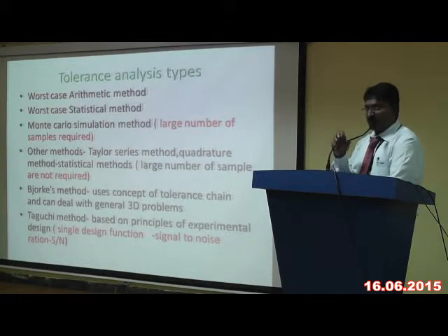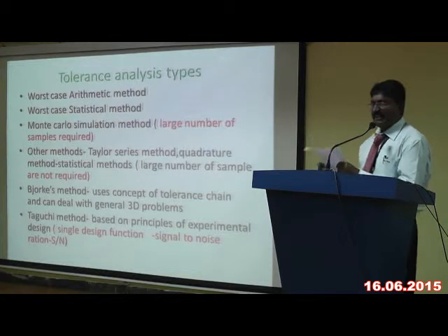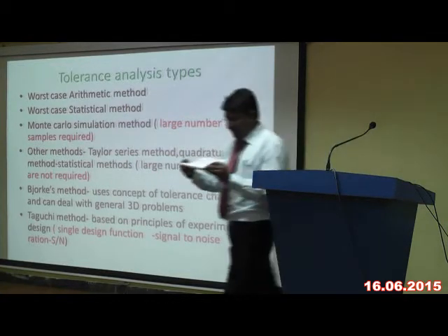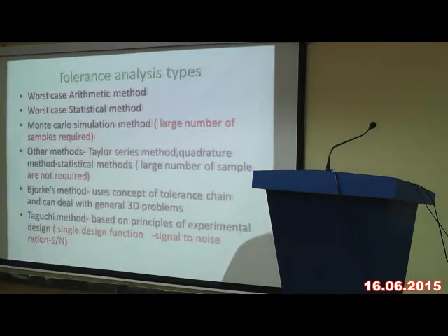And the D chain, the dimension chain, is made, and another thing is called a D tree. It is called a dimension tree, where you see this D tree is also made on one single axis. Here is one single line, and I am mentioning all the dimensions D1, D2, D3, D4, D6, and where the axis is and what the D6 is.